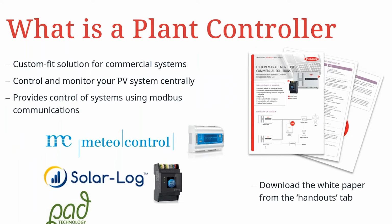But what is a plant controller? Well, it is a third-party device which is able to provide data logging. It communicates with a meter, normally its own meter rather than a Fronius one, and then it provides the control of our system using Modbus communications. There's a couple of internationally well-known devices from Meteor Control and SolarLog, which are available off the shelf from PV distributors that are able to provide this communications and provide this control.